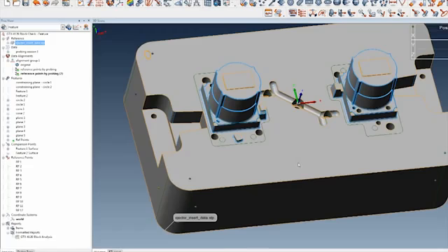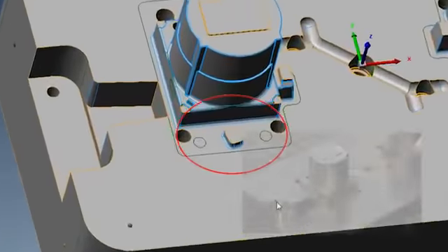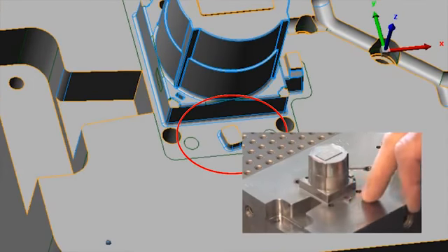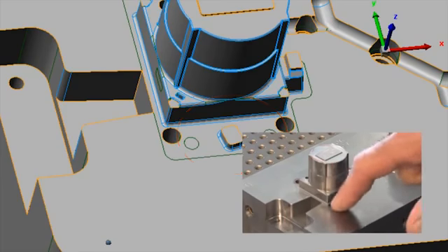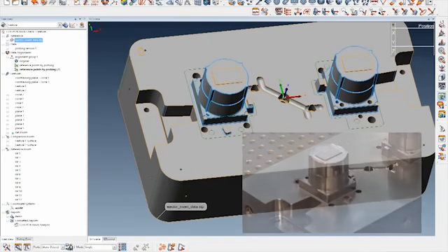This die block that we're doing some analysis on, I've got PolyWorks V12 open right now, and I've got this little feature on that die block that is in question on its location. So what I want to do is measure some of the edges of that with surface points or with some comparison points, just to see how that compares back to the CAD.